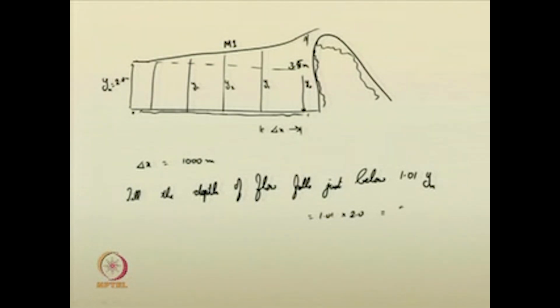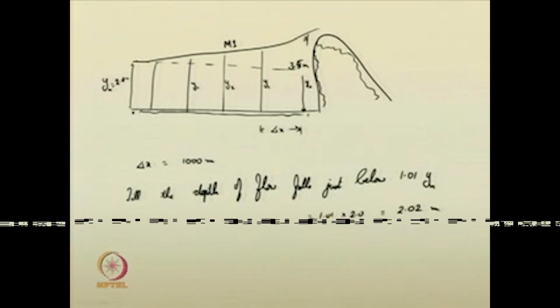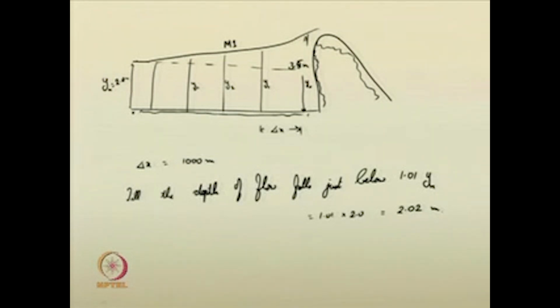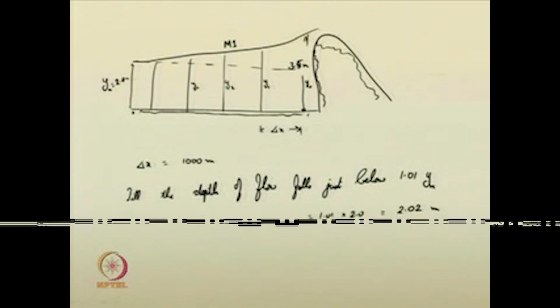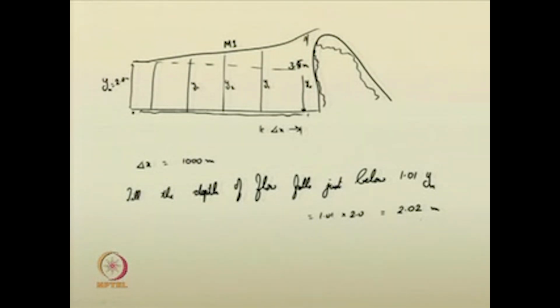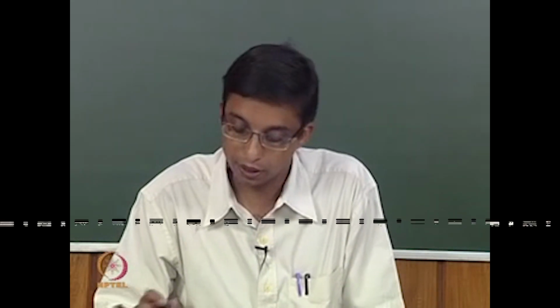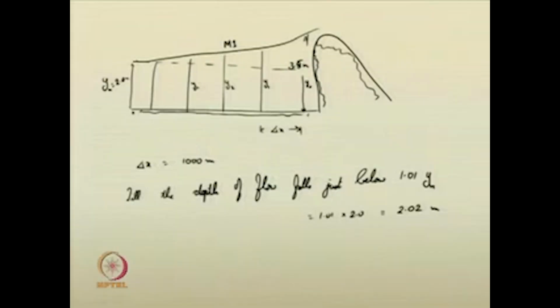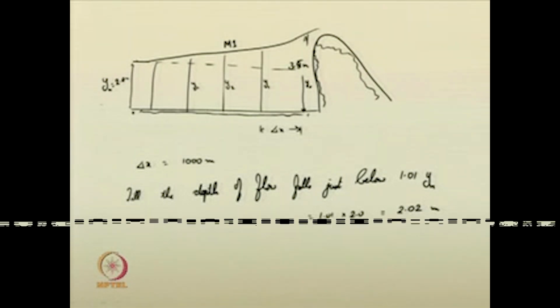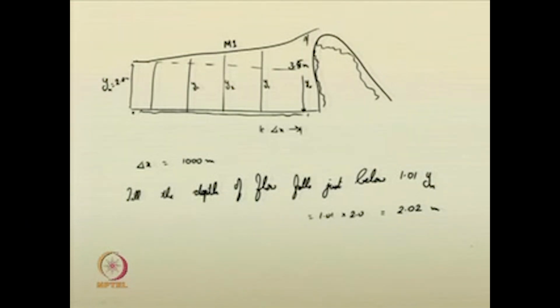So, at whatever stage in the flow computation from 3.5 meters up, whenever it reaches just below 2.02 meter, you can stop the computation. Then we are suggesting that the flow from there onwards is normal. So, gradually varied flow length can be computed up to that location. Up to this depth we are now going to compute the flow profile.